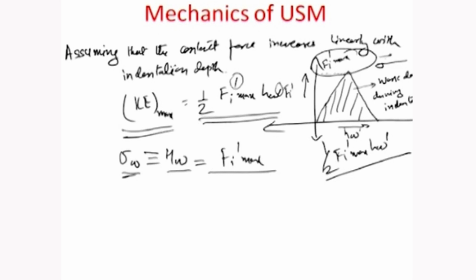At that time, if we assume that the total grain diameter projected onto the workpiece surface is capital D, and capital D is, as you already know, twice root of d Hw, where Hw is the depth of indentation. If you remember the first exercise on USM where we did this modeling, a grain with a diameter d impacting on a surface producing a depth Hw.